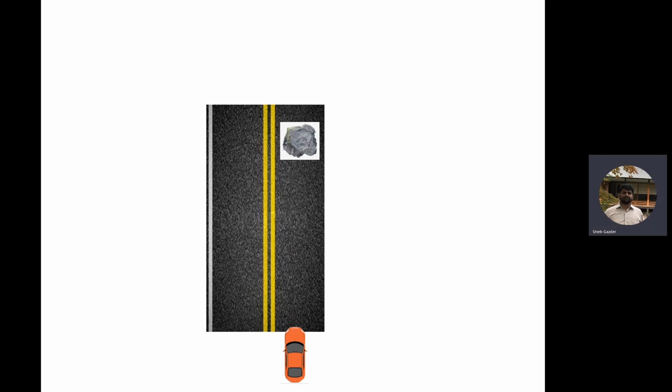The braking distance starts when he has pushed the brakes. And what did we call the time till he pushed the brake? Perception reaction time. So braking distance is not covered in perception reaction time, it is covered after that.